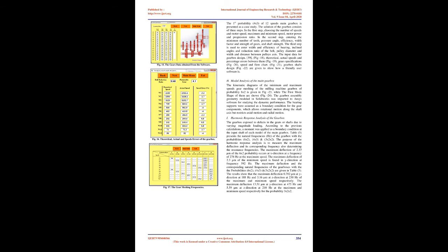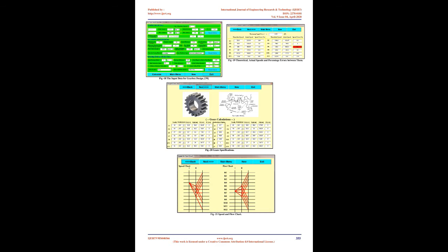It has the following form, where p is the number of speed steps and x is the characteristic of the transmission group. Kinematic diagram. It is a diagram that shows the layout of gears and bearings in the gearbox according to the chosen arrangement equation. Gears specifications and reduction ratios. The reduction ratios are calculated using the following equations. 30. Where n equals 2x1 and z is the number of the gear teeth.